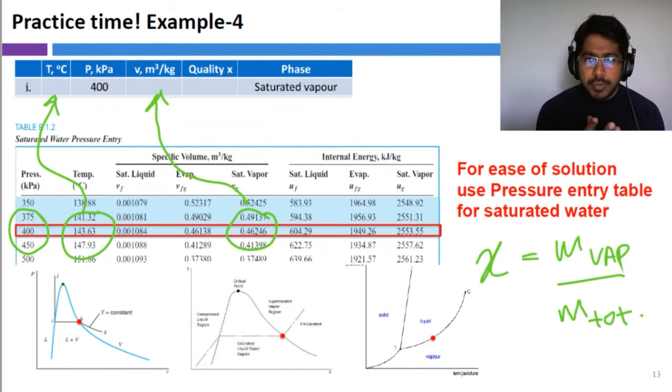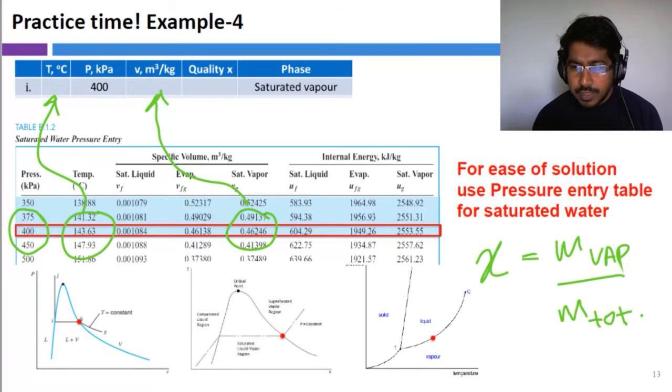We have the liquid-vapor region, and if we keep providing energy, then all the liquid in the substance will join the vapor phase, and once it has joined the vapor phase altogether, we call it the saturated vapor line at that point, right? The boundary condition. So there we don't have any liquid, therefore x is going to be 1. So all of your answers are correct.